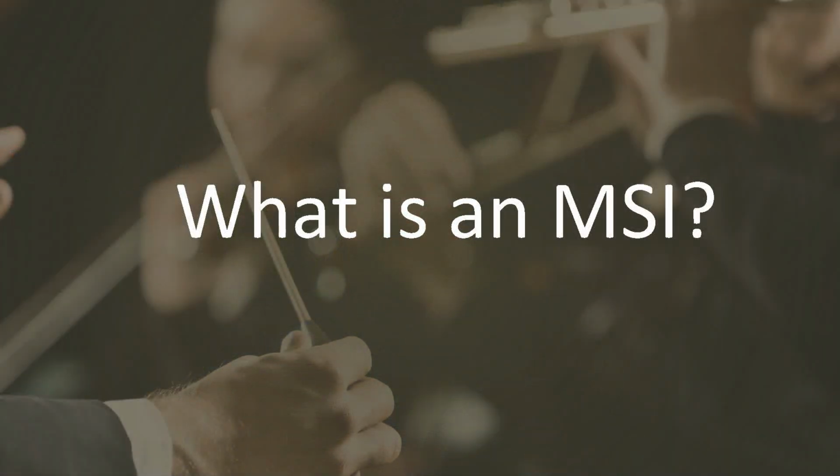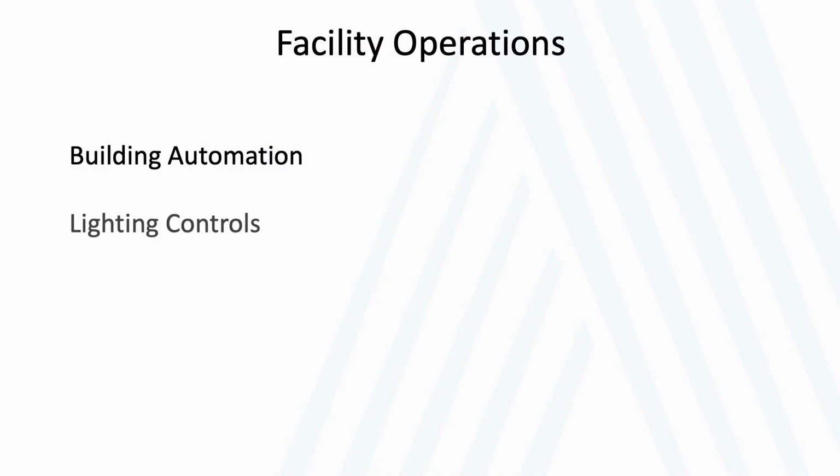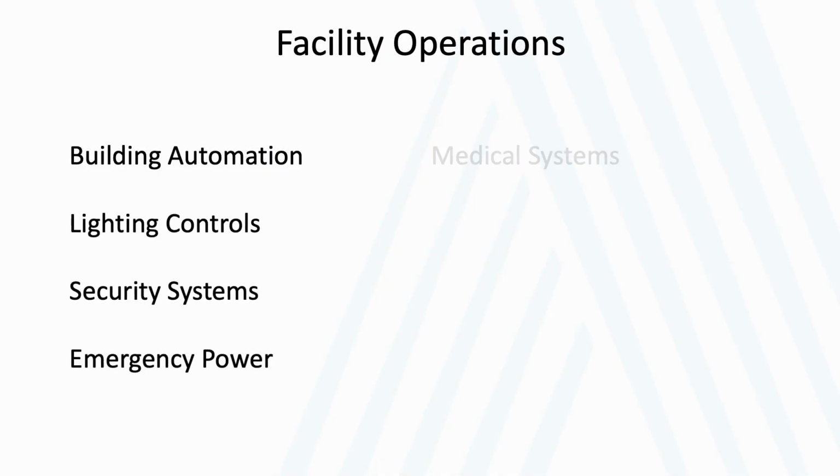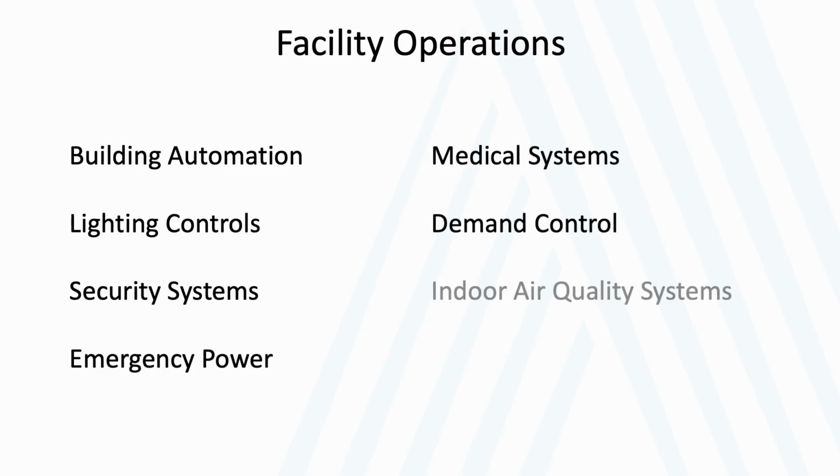And what we're talking about with master systems integration, or MSI, is really taking a look at a lot of these traditionally siloed systems, things like building automation, lighting controls, security systems, emergency power, medical systems, demand control and indoor air quality systems, fire life safety, and integrating those in a new way to accomplish new use cases.